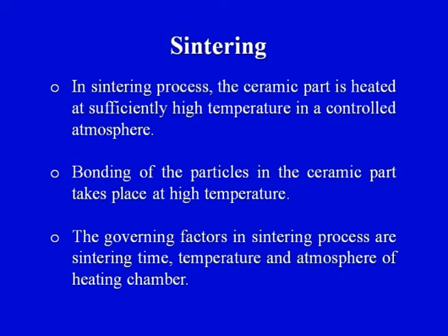Those are the sintering time, for how long that temperature should be maintained, because this is being done at an elevated temperature, at a higher temperature. What is the period or the duration for which the ceramic part has to be subjected to an elevated temperature? So, first important variable is the sintering time. Another important variable is the sintering temperature, that at what temperature the process has to be carried out, and the next is the atmosphere of the heating chamber, which we have already seen has to be controlled. So 2-3 important points have to be taken into account, that is the sintering temperature, the duration for which the temperature is maintained, and finally the atmosphere under which the sintering is being carried out.